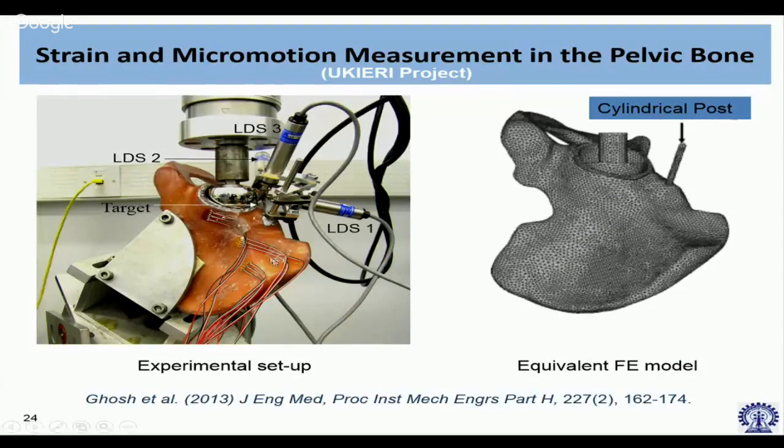You know, it's a very good solvent, and you can see some traces of white on the surface still there, but we actually put 5 strain rosettes on different locations, just random, and try to measure the strains at these locations and compare it with the DIC measurement.